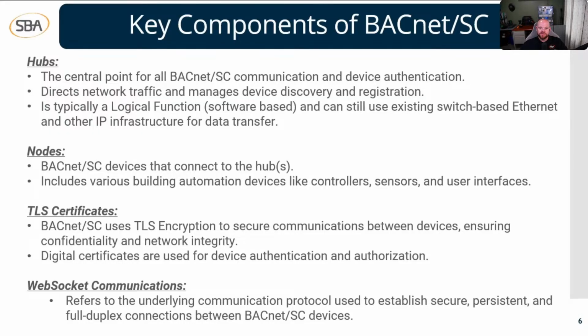And then the last thing here for key components of BACnet Secure Connect are WebSocket communications. Now, this has also been a protocol for a while. So this is tying back into existing systems and still using older protocols to communicate. WebSocket communication refers to the underlying communication protocol used to establish secure, persistent, and full duplex connections between BACnet SC devices.